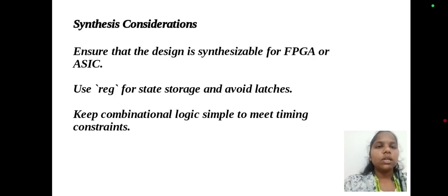Synthesis considerations: ensure that the design is synthesizable for FPGA or ASIC. FPGA or ASIC is implemented with logic gates. Use registers for state storage and avoid latches. Keep combinational logic simple to meet timing constraints.